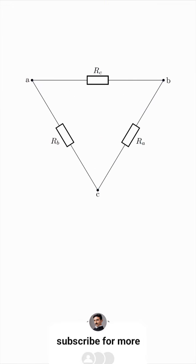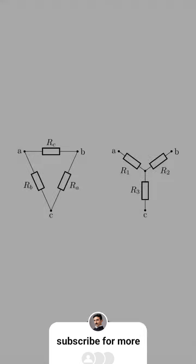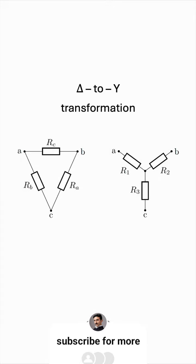Resistors RA, RB, and RC form a delta interconnection because the structure looks like the Greek letter delta. On the other hand, resistors R1, R2, and R3 form a Y interconnection because the structure looks like the letter Y. The objective of a delta to Y transformation is to transform the interconnection of the three resistors between nodes A, B, and C from one structure to another.